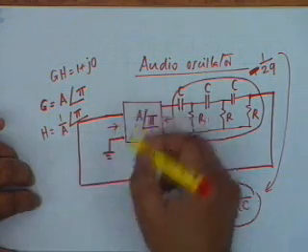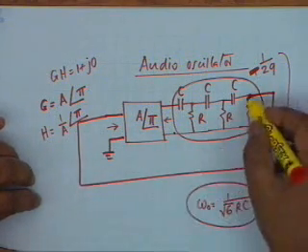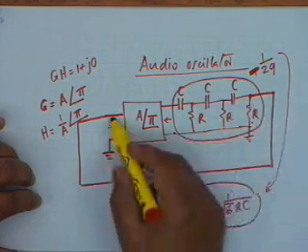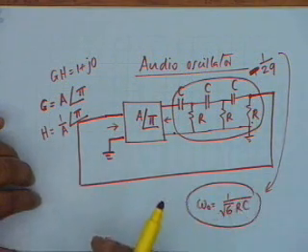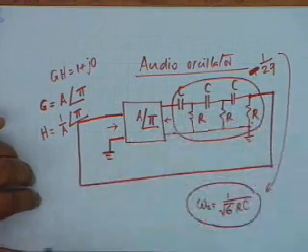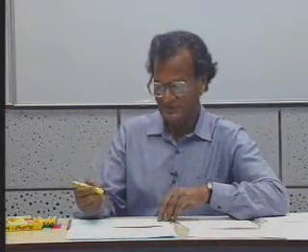Similarly, the input impedance of the transistor is not infinity, that is, capital R is affected by the input impedance of the transistor. Input impedance of the transistor approximately is R pi, alright. Therefore, the calculation shall be a bit more involved, and the actual circuit of a BJT oscillator